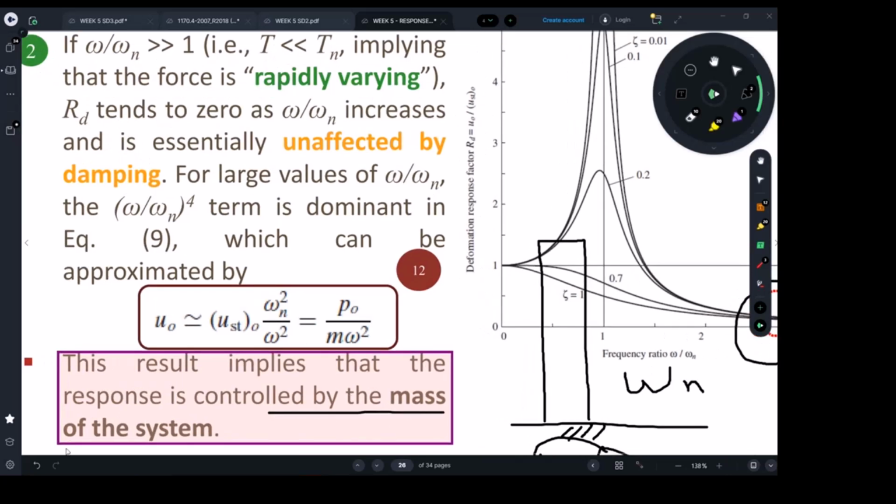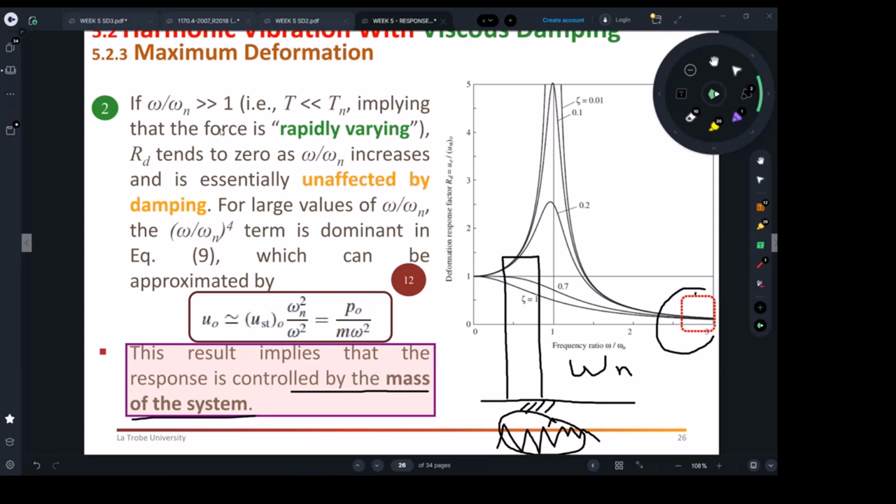And basically, that's what I was saying. It is controlled by the mass. The vibration is controlled by the mass, and here the mass of the building itself is kind of leading the show. And yes, there are high vibrations that can come from tram lines or the tunnels from the trains under the ground in the city. But those vibrations, sometimes you can sense them if you walk next to them, but the building won't really shake because of those vibrations, because of this relationship, because the ratio between the forcing frequency over the natural frequency is way, way above 1.